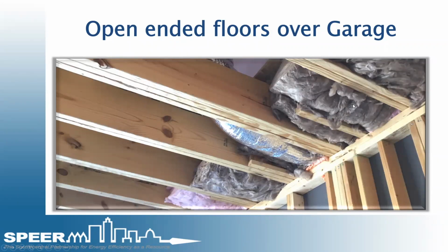But the flooring itself, the insulation on top of that top plate that's going over from the garage to the interior, needs to also have blocking there and needs to be sealed. There's polyseal around the duct that's going through that. When I looked through that, it was blocked. But the insulation cannot be exposed to an unconditioned attic over the garage. So between all of these floor joists or ceiling joists of the garage, all need to be blocked. It's going to be sheetrock from the bottom, blocked at the end, and OSB at the top. So that's 6-sided encapsulated. If it's left open, this insulation will have air move right through it.